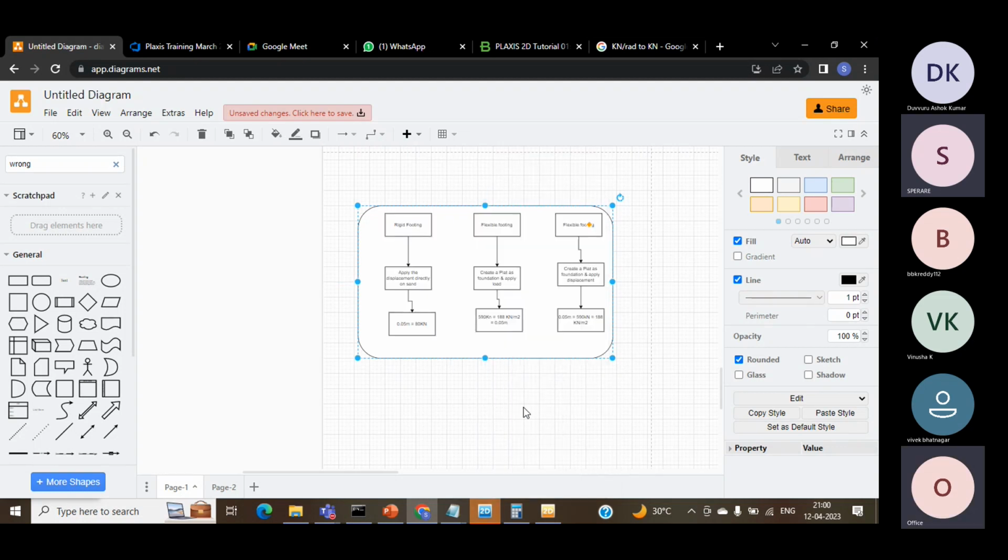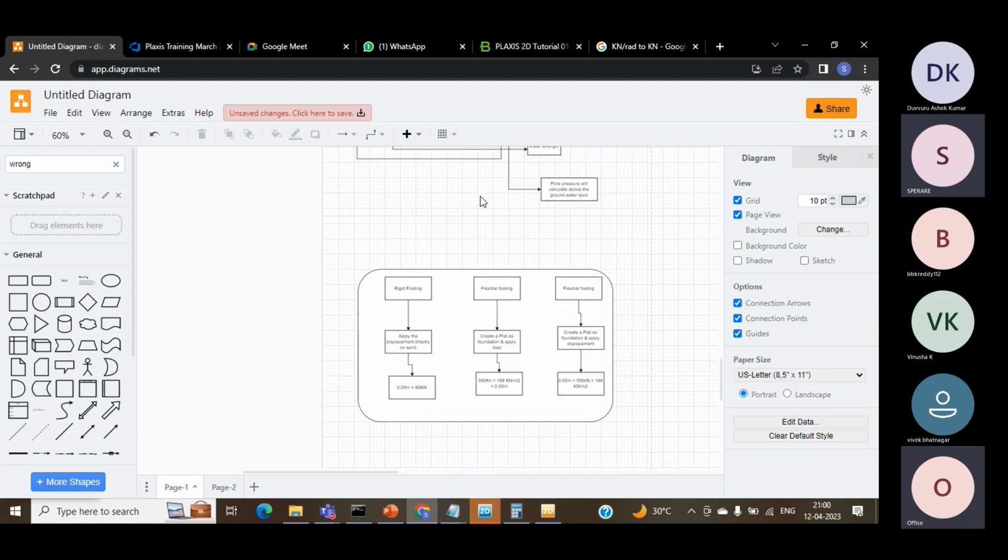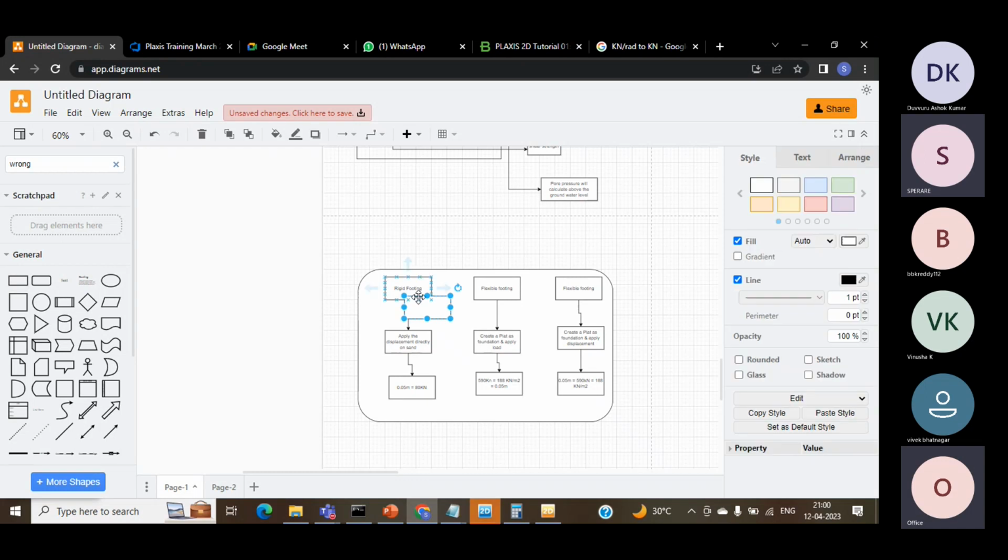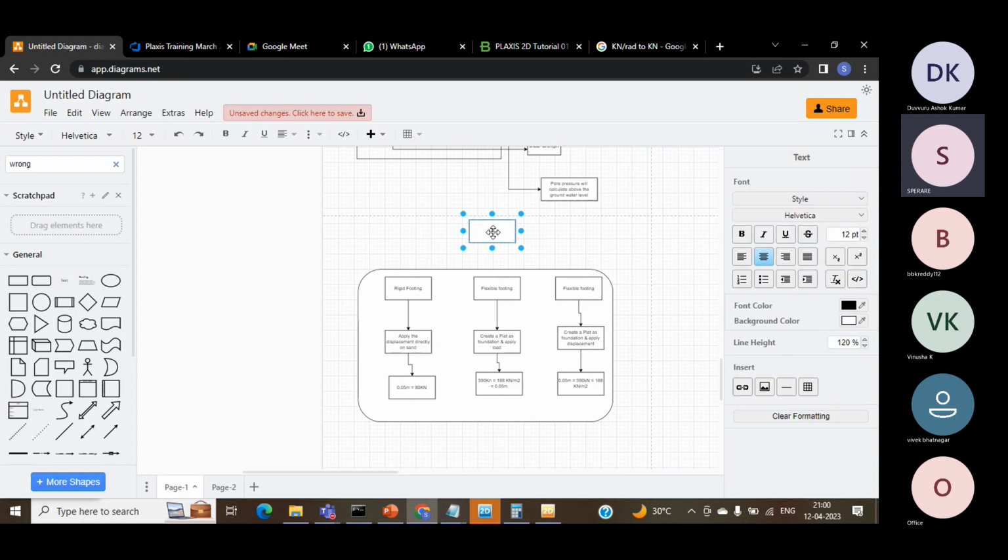He is not considering 360 degrees, he is considering 180 degrees. So if you consider a circle up to a meter, maybe considering 1 meter, the section is rotated in 180 degrees. Yeah, so he is multiplying with pi, not 2 pi. Yeah, visualization wise, you are applying it only for half, but the software will consider the other side as well.